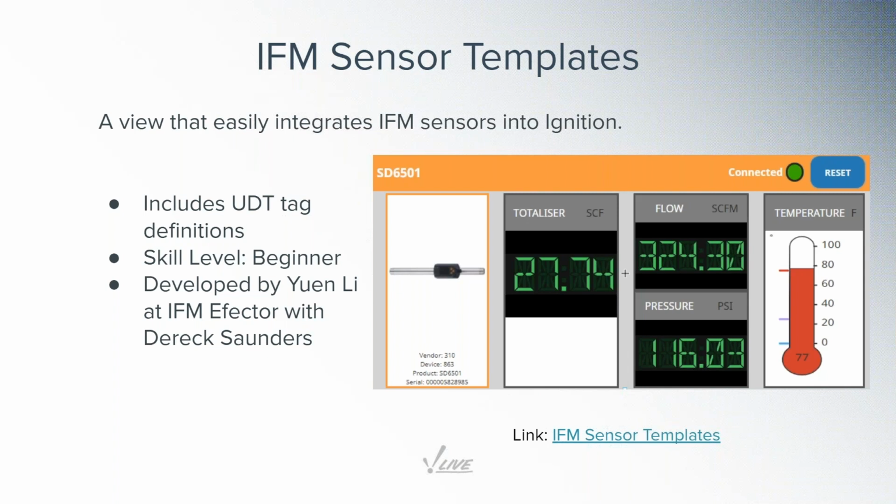Yeah, and there was a quick question, which is, what is a totalizer? You want to quickly answer that question? Yes, absolutely. So the totalizer is measuring the amount of air that's passed through the pipe, right? So that's good if you're looking for energy monitoring, you want to know how much have you used already of air, or in some cases flow, a fluid of some form.